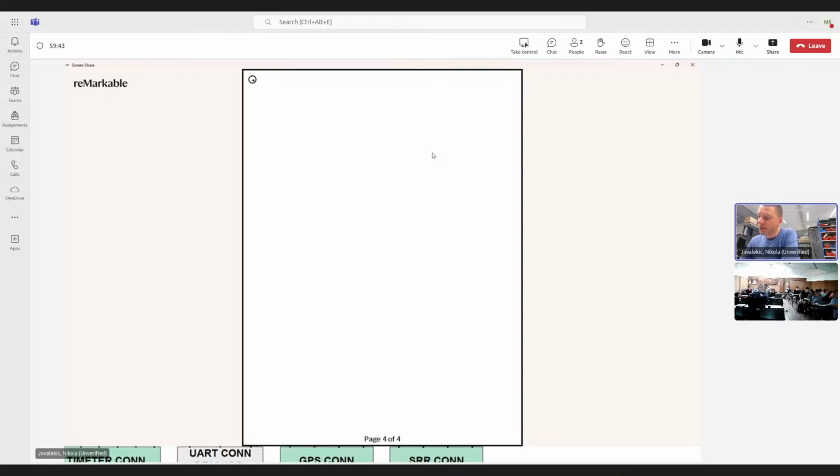What do you have actually in practice? You will have this trace interconnect, but around it, you will actually pour the copper plane, which is ground, on the whole layer. So this will all be a ground, but it will have openings where the traces are.